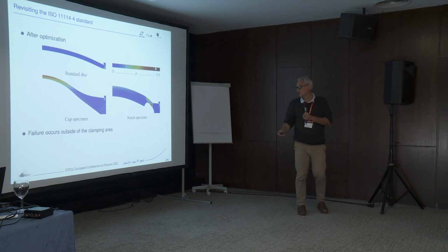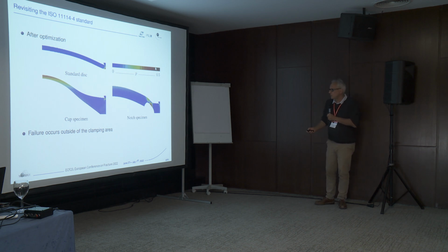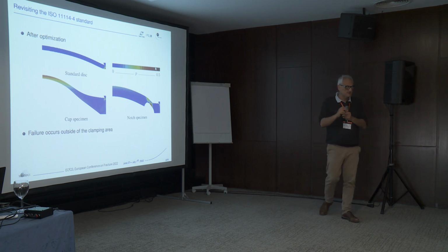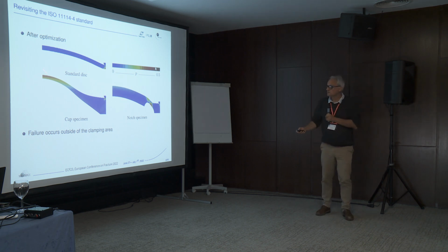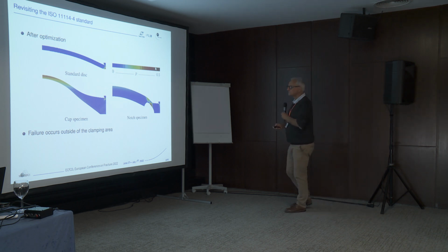not that interesting? This problem is solved with a notch specimen because we have a high concentration of plastic strain on the pressurized side. The only drawback of this specimen is that the volume of material which is stressed is very small compared to this one where you have the central area which is more or less evenly stressed.